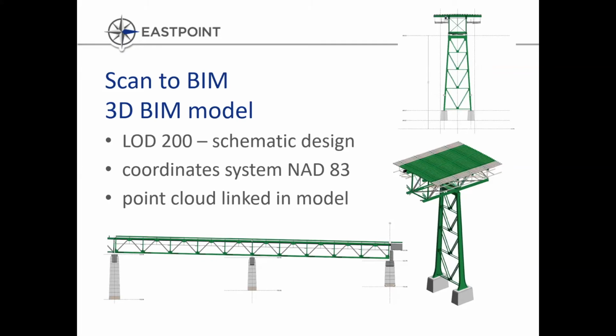In order to start the BIM model prior to scanning, we used the original 1950s construction drawings, drawings from the third lane job, and shop drawings from the Big Lift project. These were provided as reference from HHB. Once we had started the scanning, we linked the point cloud into the modeling environment and validated the BIM model using the point cloud.